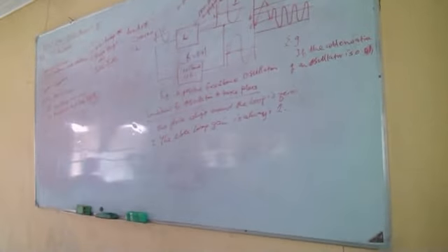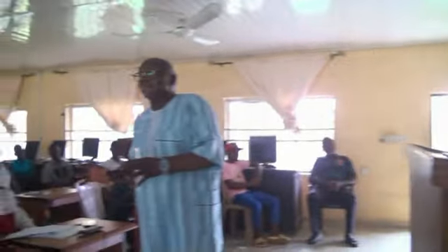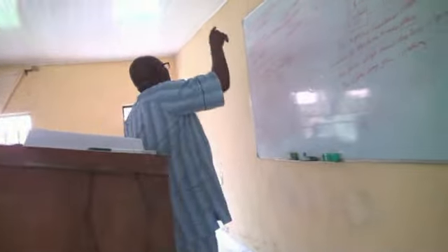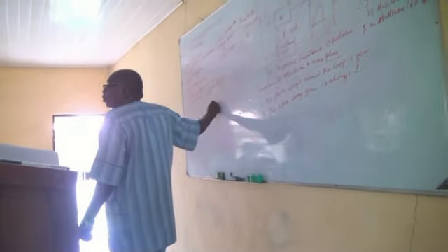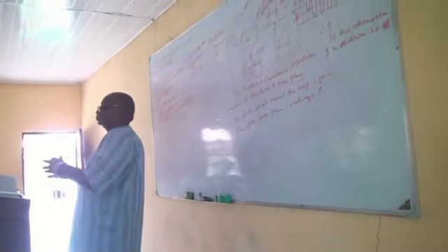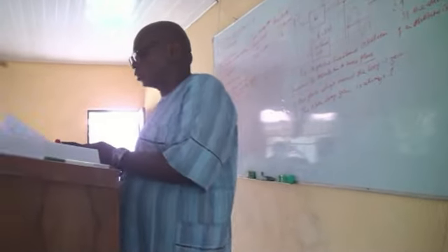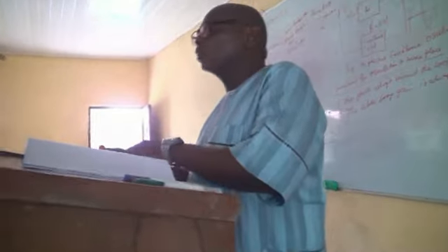Are you getting my point? So if you are doing any design and you have to use an oscillator, and you are using an RC oscillator and your frequency is 2 megahertz or 1.5, that circuit will not work. That's a practical thing. It will not work. You only waste your time, waste your energy, waste your resources.